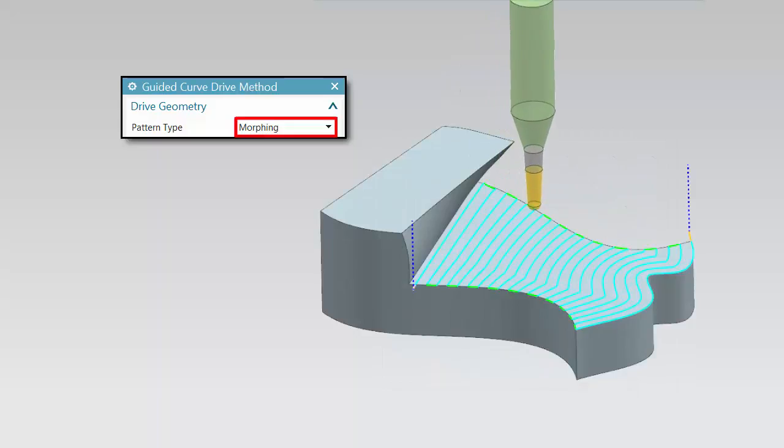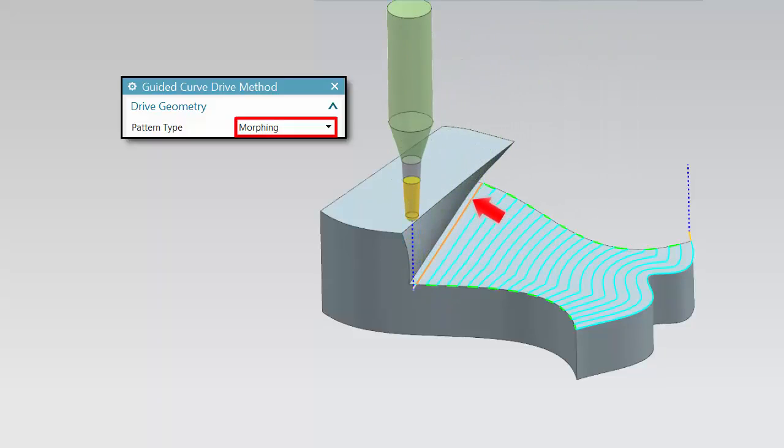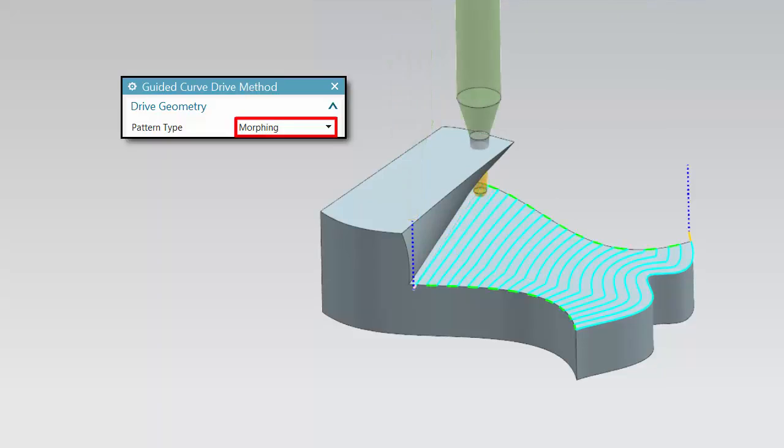For variable guiding curves operations, if the tool cannot reach the specified curve due to a double contact condition, the system will generate a guide curve following the double contact trace. Although portions of the tool may show a collision while working on the pattern, since the operation has the tilt tool axis embedded, the final path is collision-free with maximum coverage.